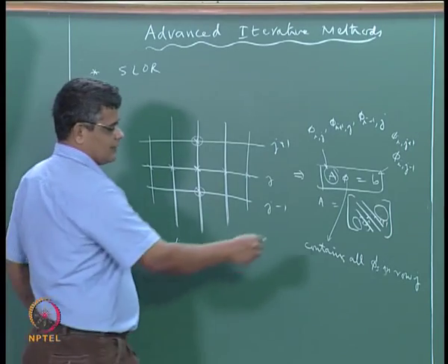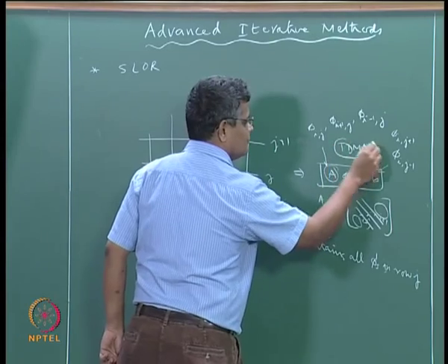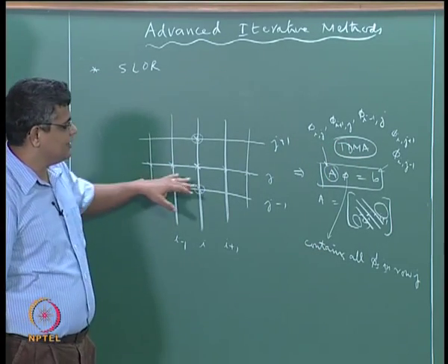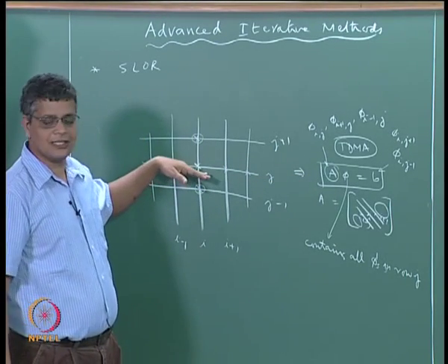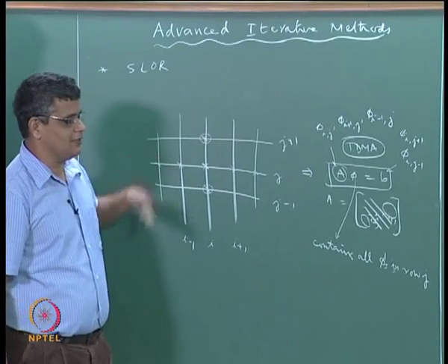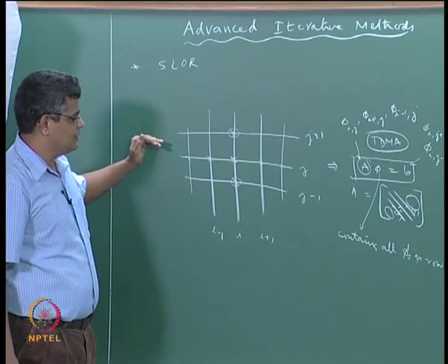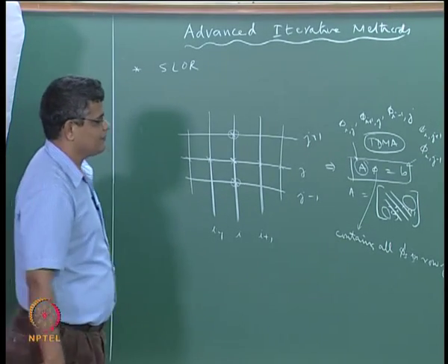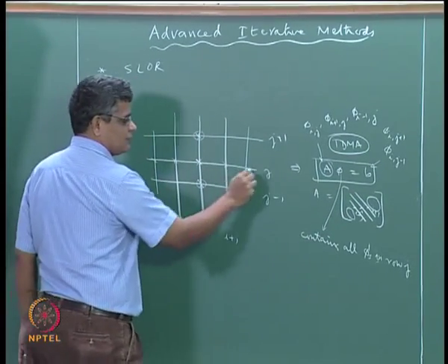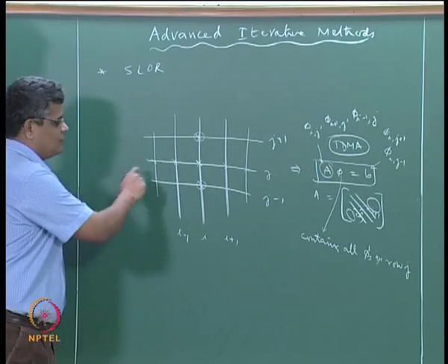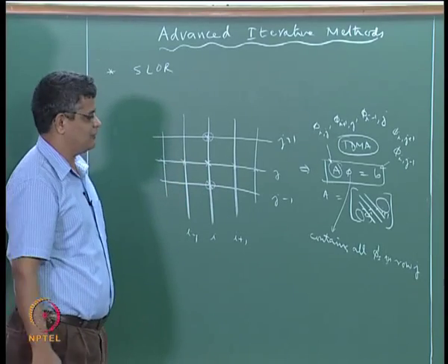Okay. So if we solve this using the TDMA scheme or the Thomas algorithm, given that effectively this becomes the discretized equation of the one dimensional Laplace equation, we know that this will satisfy the weak form of the diagonal dominance condition, and therefore we can apply the Thomas algorithm here and solve for all these points efficiently, because the number of points, if this is m, the number of computations required will be 13 times m or something like that.